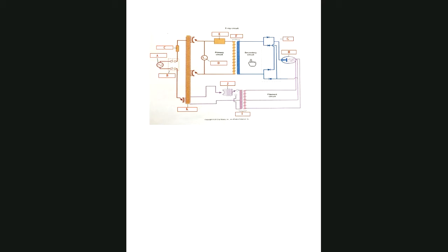You have to be able to read them and see: if this is a step-up transformer, then I expect the voltage to be higher on the secondary side than on the primary side. By the same token, if that voltage goes up on the secondary side, the current is going to be decreased on that secondary side.